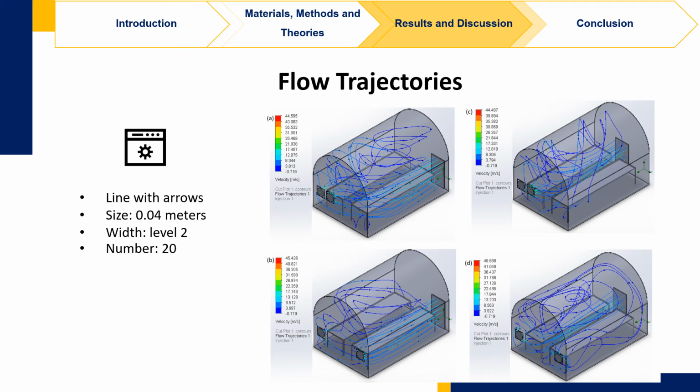When the door was placed closer to the fan, the air flowed faster and circulated better, as in cases C and D. Some amount of air rises to the ceiling, then slowly travels toward the fan, whereas some flows directly to the fan position. Although the velocity in case D is great, the flow trajectory isn't consistent across all locations